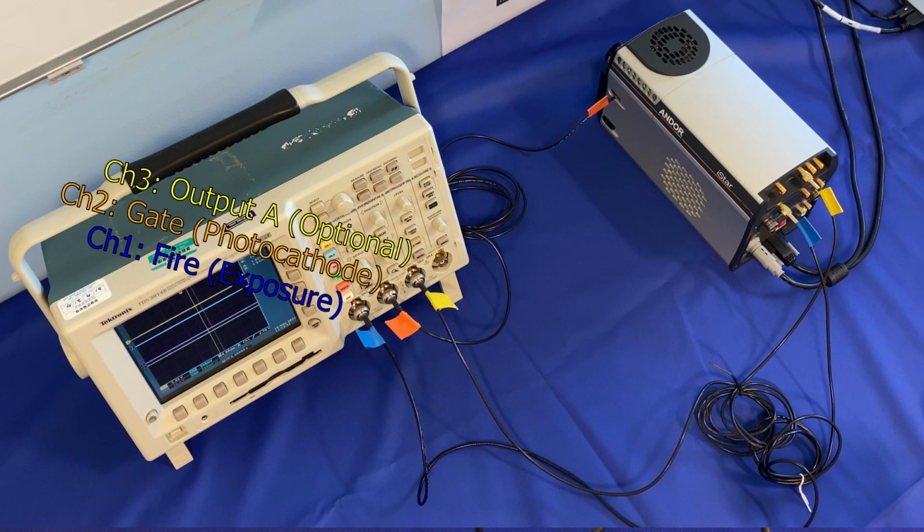One thing that's quite important to mention is it's important with these cables to match the impedance of the system, such that you don't get any distortion or reflections in your oscilloscope trace, which can distort the waveform and make it harder to see exactly when your timings are falling, etc.